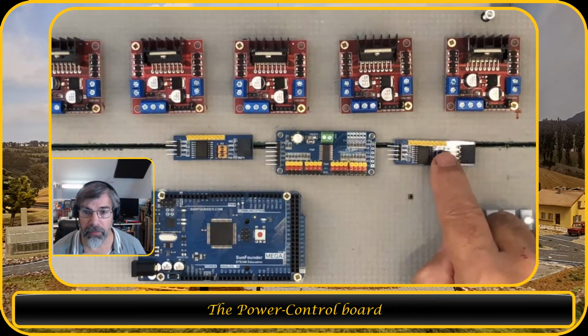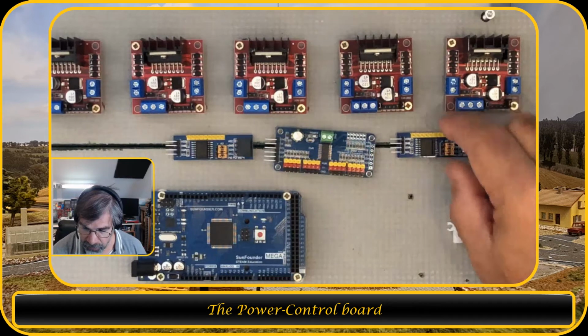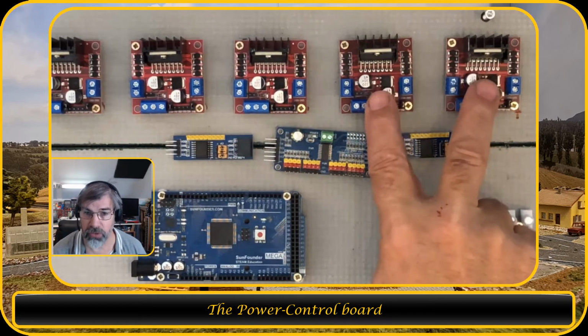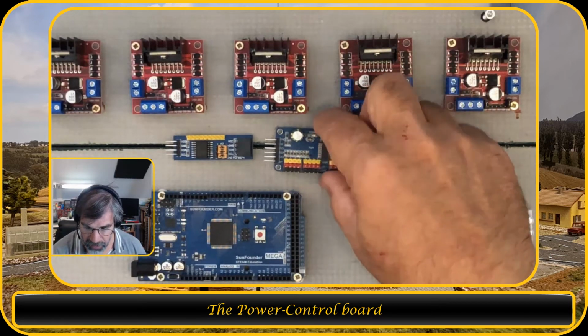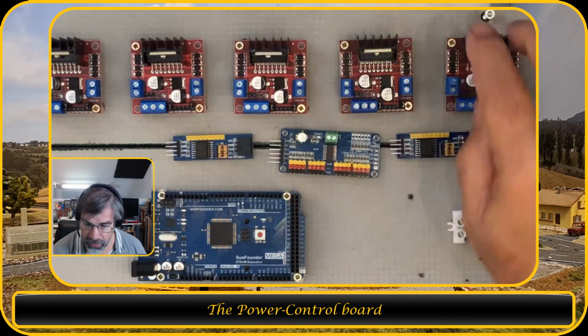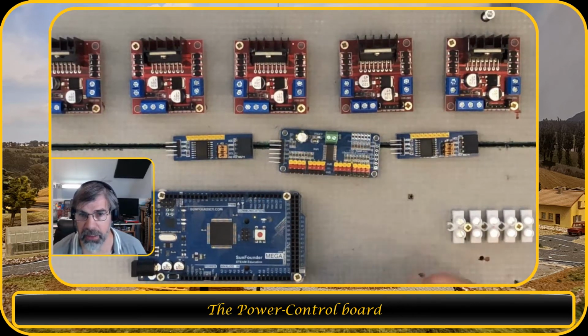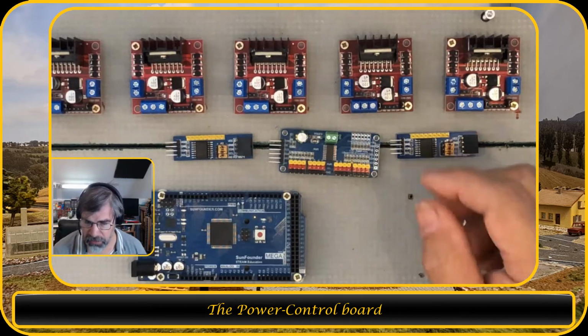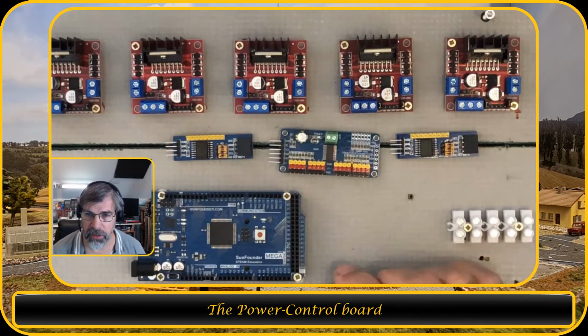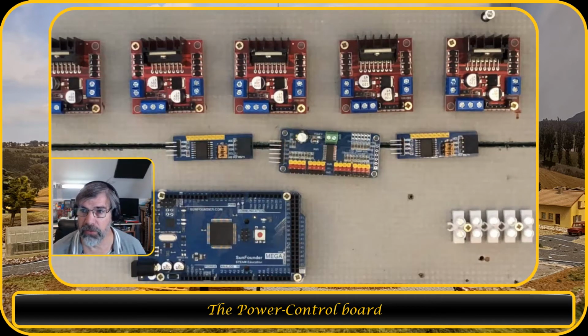Then we have the input-output detectors over here, and I will need to position them in the correct way, but I need to have one for each 2 drivers, so for each 2 motor drivers, and this will be the PWM signals to control the motor drivers. On top of that, there will be some current sensoring done to detect the train. So when there is a train in the track, on that section, it will have a resistance, it draws a little bit of current, so I will put some current detection sensors in between, but that will be for a later video.